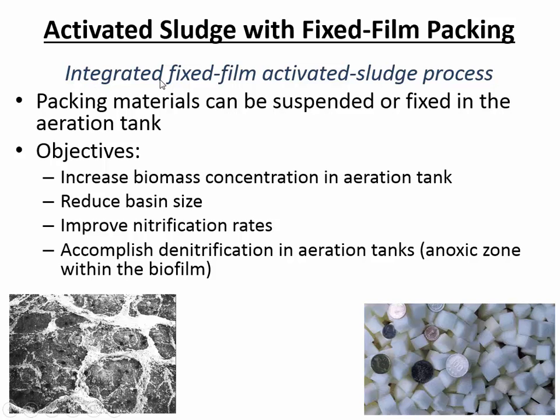Integrated means that the media is put inside of the aeration basin. The difficult thing, though, is keeping these little plastic foam pellets inside the aeration basin. And so you have to have a net or a mesh to make sure that they don't exit the aeration basin, because if they get into the clarifier, then having a bunch of foam pellets could clog the clarifier.